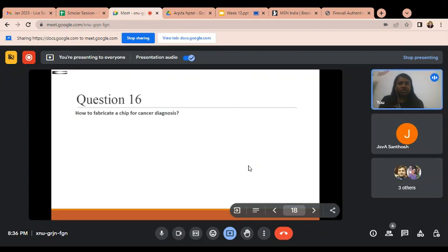First actually there is a substrate, then there is a silicon dioxide layer, because we can't deposit the electrodes directly on the silicon wafer. That's why we need the silicon dioxide layer. So on that silicon dioxide layer, we have to first deposit some contact layer, like the gold or chromium gold layer. Then we will follow the photolithography process, like we discussed earlier how to pattern or transfer the chromium gold. So this is the wafer fabrication process to fabricate this IDE pattern or interdigitated electrode pattern, the chromium gold pattern.